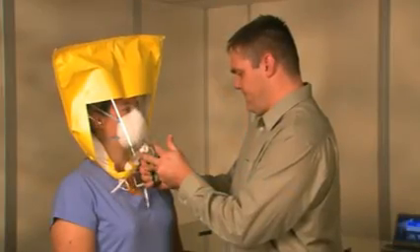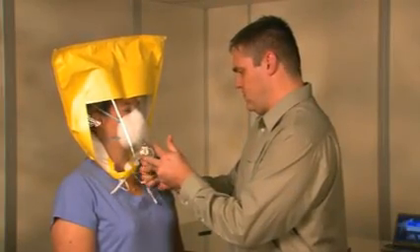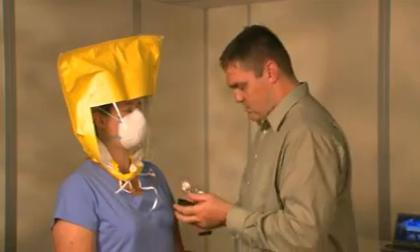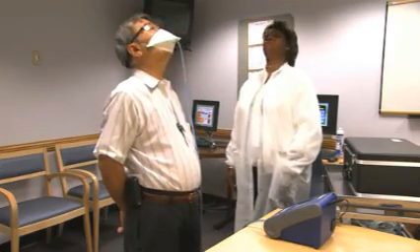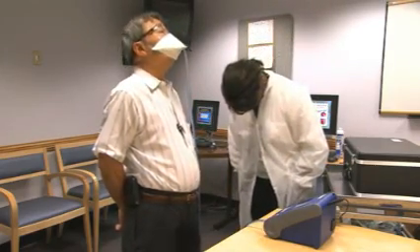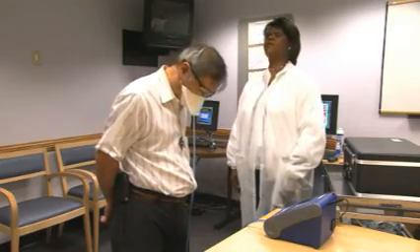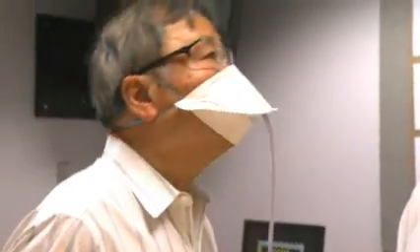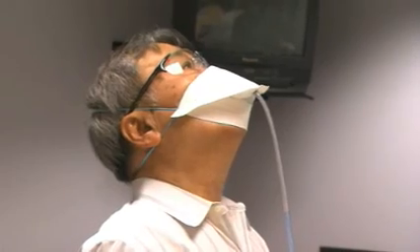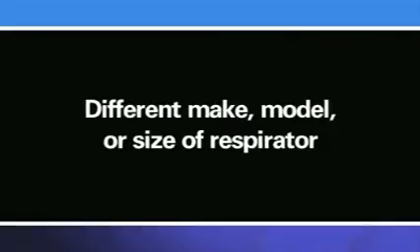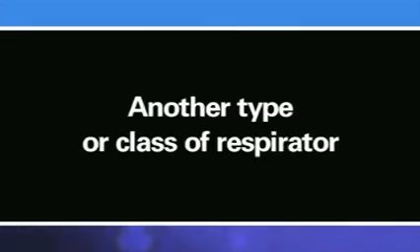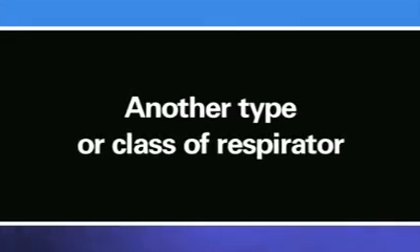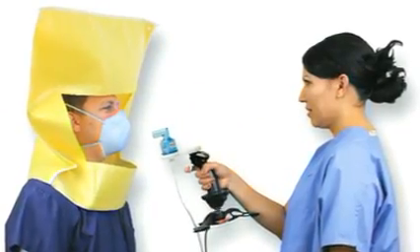So before you wear a tight-fitting respirator in the workplace, you must be fit tested with the specific make, model, style, and size of that respirator. The purpose of fit testing is to be sure that the face piece of the selected respirator fits adequately to your unique facial characteristics. Some people cannot be fitted with a particular respirator. They may require a different make, model, or size of respirator, or they may require another type or class of respirator.